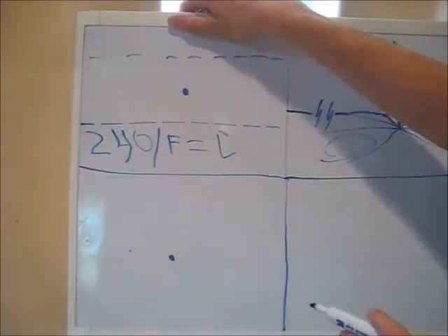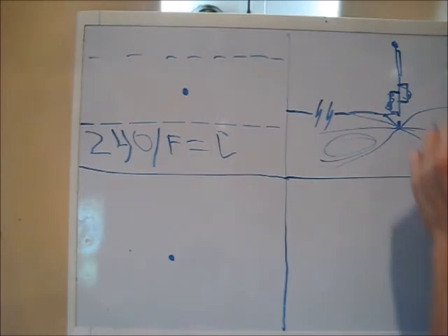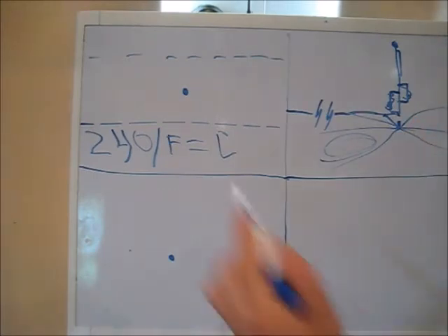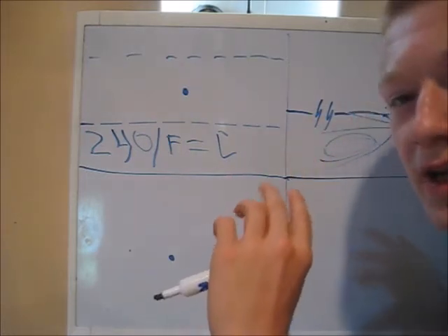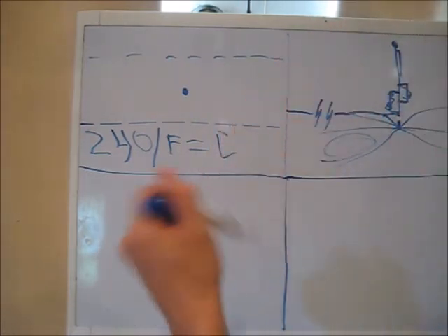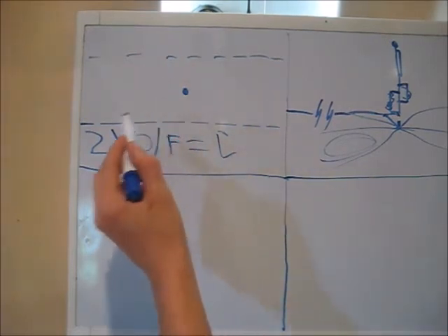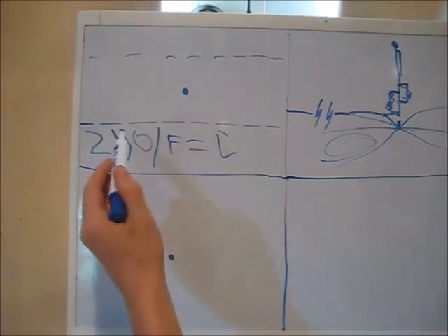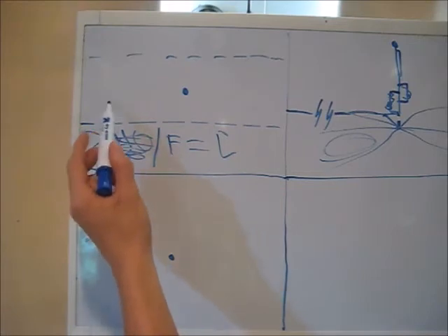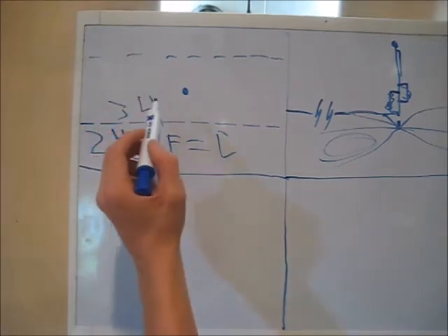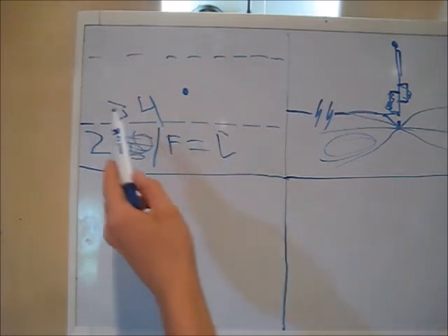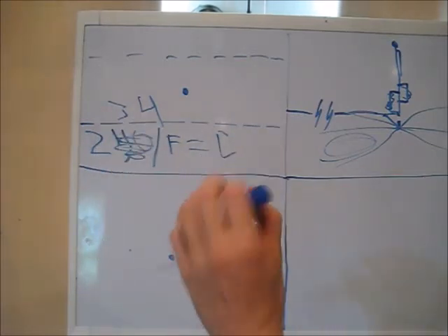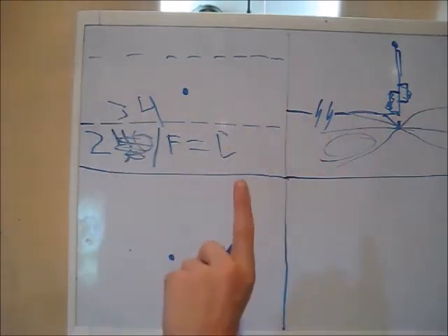Now this is for a single band version. Like I mentioned, some of these will have traps. These change the SWR on certain bands. So if you want to make it for one band only, and you're literally taking a piece of copper wire and running it straight up in the air, then you use a very similar formula, but instead of using 240, you use 234. So 240 is for radials, 234 is for verticals. That is for a single band vertical.